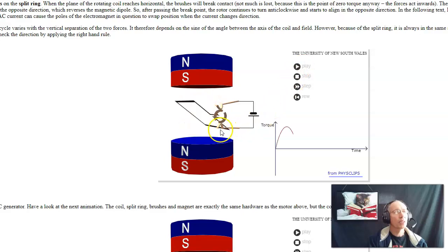What DC motors look like, DC motors have this commutator. When I go through the zero crossing, I flip the leads. And what that does is, instead of getting a plus minus voltage, I always get a plus voltage. So this is a DC generator. It has the average DC value. This is also a DC motor. Apply constant voltage and it'll spin.